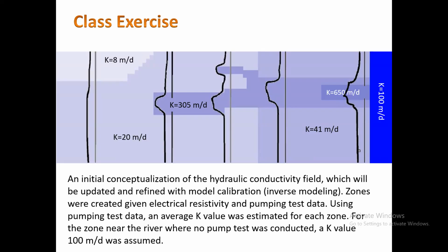Now let's say I have a river here, feeding the groundwater, a gaining stream or a losing stream. That will also affect my H value, right? If I put a pumping well here, W, and I start pumping Q out, what will happen to my head here?